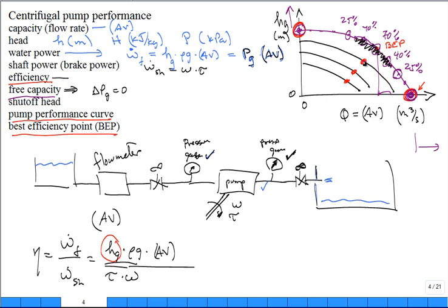So they'll say also for this one, they'll come down to the flow rate, 1.1, 0.8. They'll get a region like that. And this one, and then this one. And so they'll get a region that's a map like this. And they'll say, for that casing, with all of our impeller designs, that's where you should run this pump. Okay? That's where you should run with this pump.